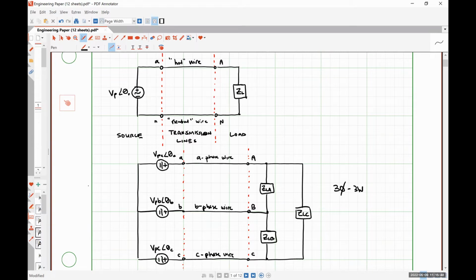We can get away from this by introducing extra poles into the motor. So it's still going to be effectively fractional relations of that 3,600, and it's going to operate at a single speed. There are devices which are called variable frequency drives that enable motors to operate at different speeds.